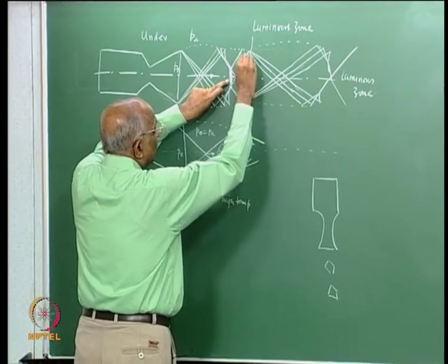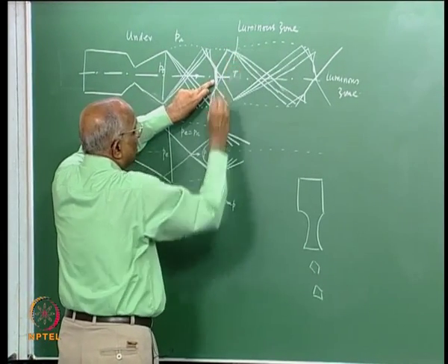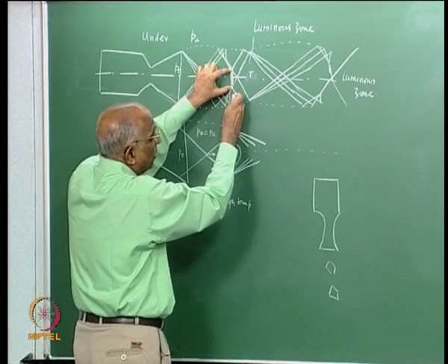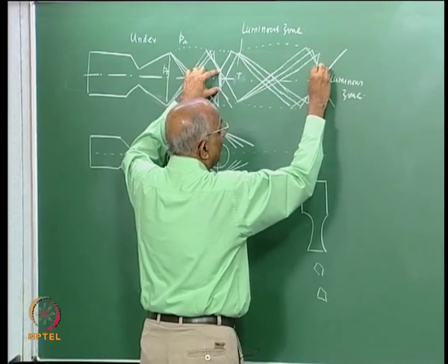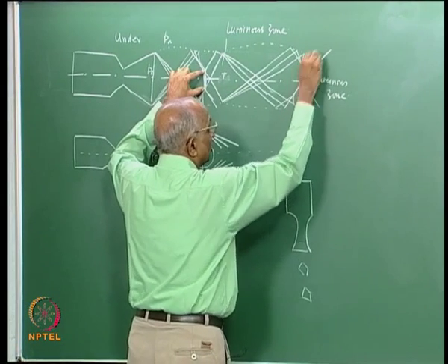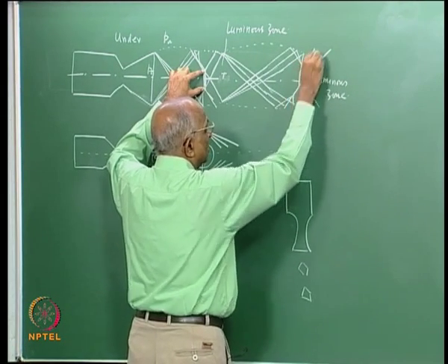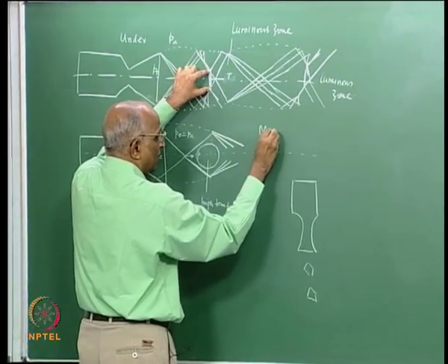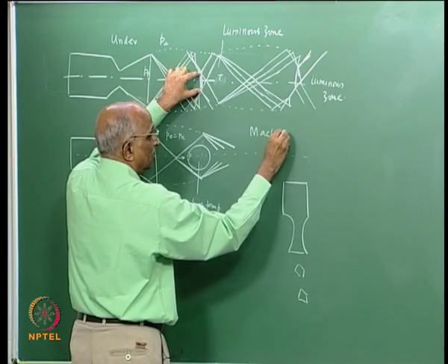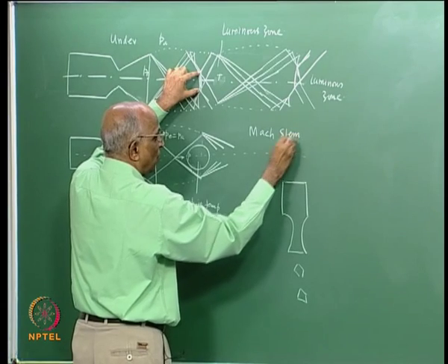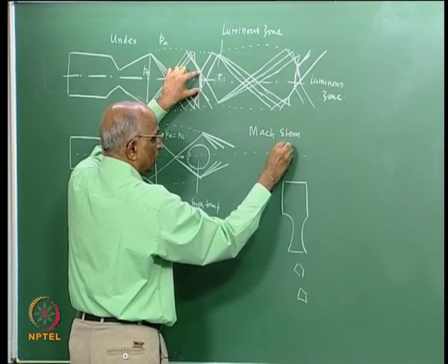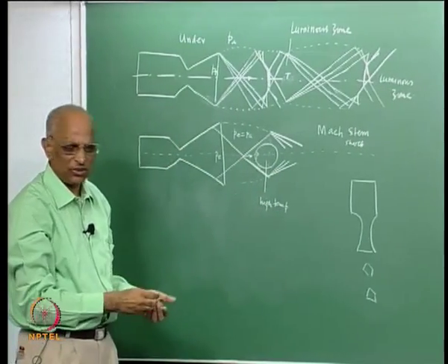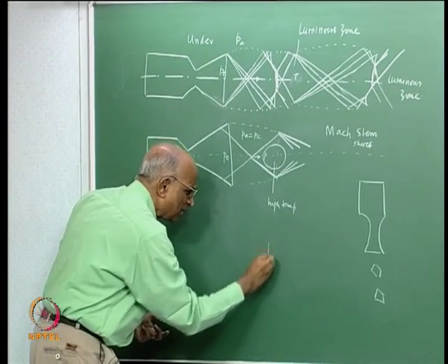The shock pattern therefore continually changes, and you have a shock structure forming over here. Similarly, I will have a shock structure which is getting formed like this. That is, the simplified picture gets a little complicated because I have a Mach stem shock which is formed, and that is how you see the diamonds in those particular pictures. The diamond pattern is actually something like this.